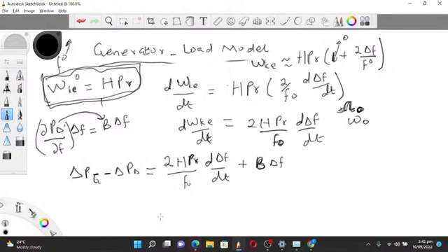So let's skip the reading part. You should know the meaning of dead band of governor. When we talk about dead band of governor, you know that when demand increases, the rotating parts slow down. Your governor is supposed to respond to that change and then increase frequency. However, it doesn't sense the change immediately. The time before the governor takes action, that's what we call the dead band of governor.